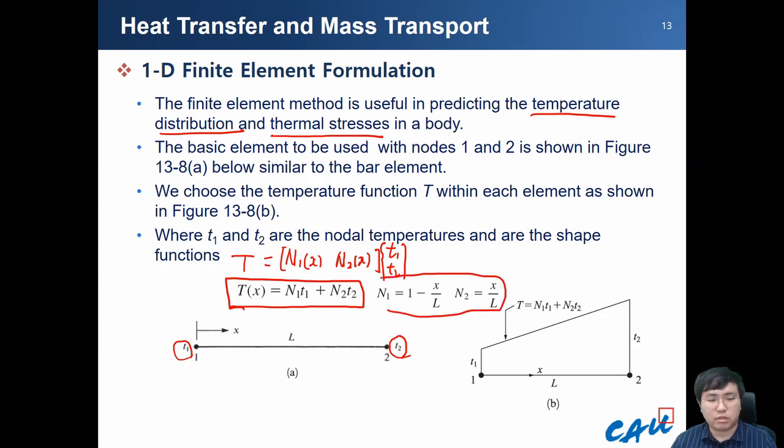We are going to take the same interpolation function as in the truss case, so that at the nodal points we obtain the exact temperature values, and inside the element we interpolate using the linear interpolation shape functions.